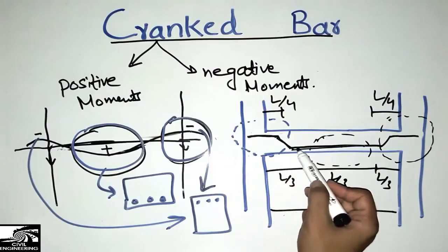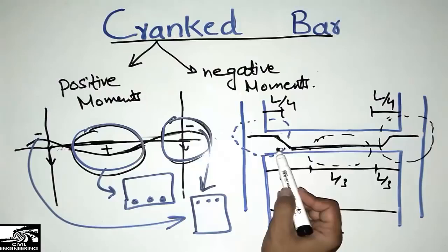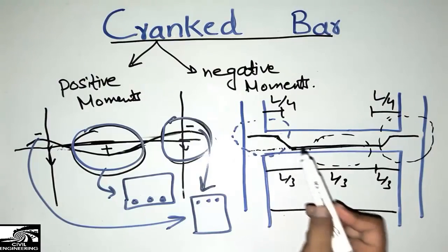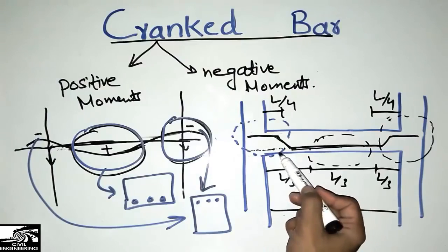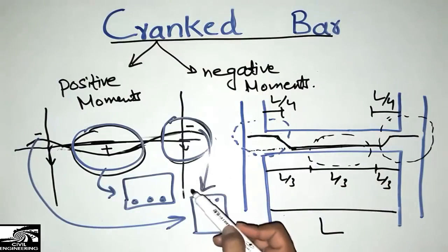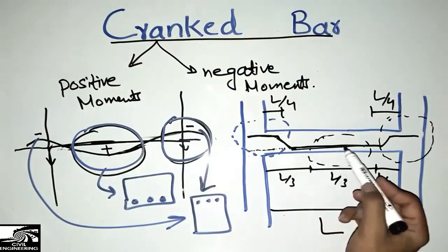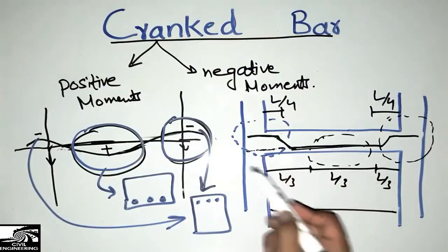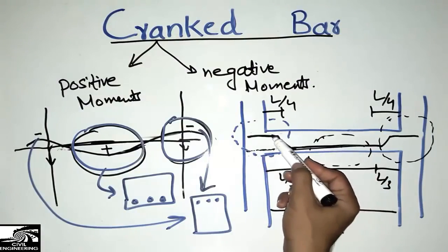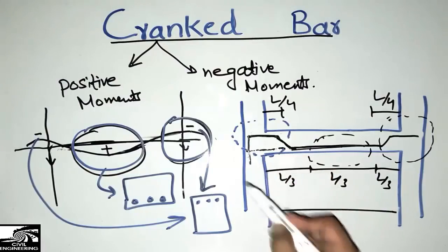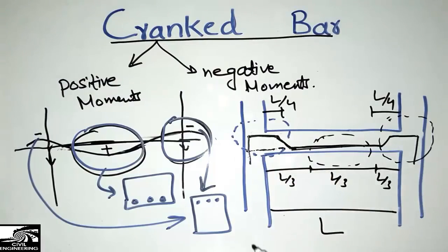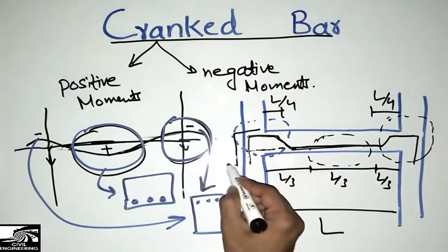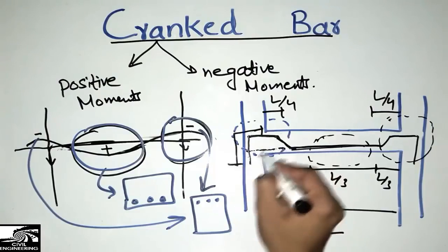section. Why? Because there is no use placing the reinforcement here in this positive direction, because there is no positive moment acting, but somehow we place the minimum reinforcement throughout the joint. But we don't allow all of the bars to move inside the joint. We bend the bars and move upward into the column, and it bends this way.